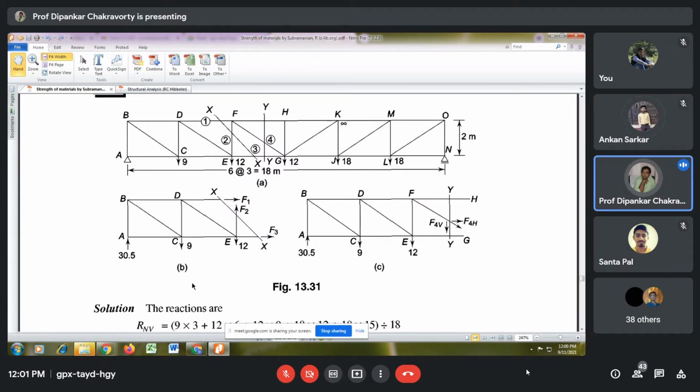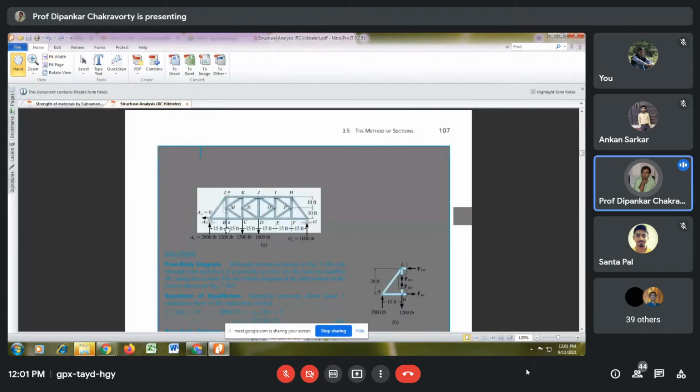But sir, the horizontal component of FBC is there. The force on the BC member will act on AC, the reaction at A, I think. I understand, but for a particular member, you cannot get two different forces from two different joints. So if you look at joint A, with respect to joint A, it is zero, and therefore it will be zero. Are you all convinced? Yes, sir. Okay. Now I'm just putting this discussion on hold and coming to identification of zero force members.